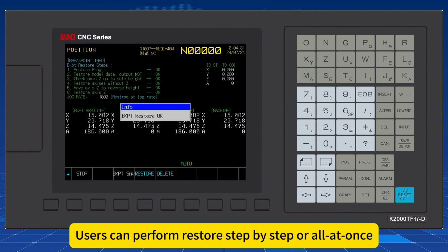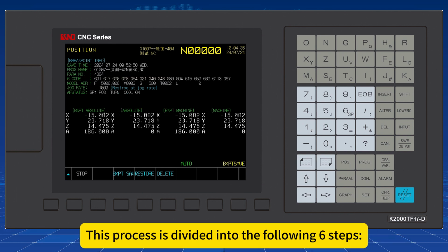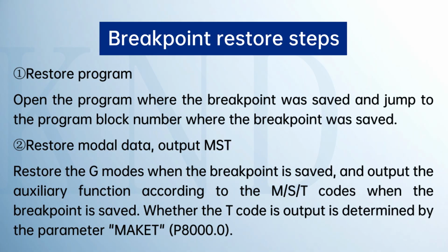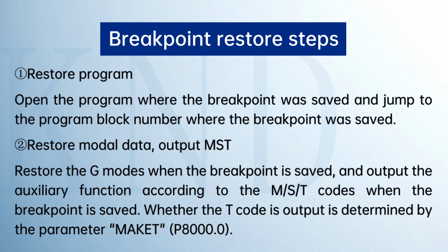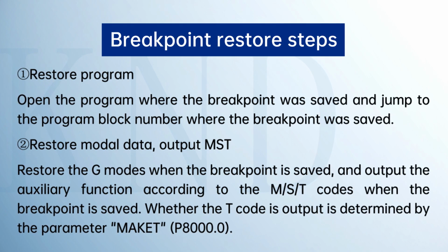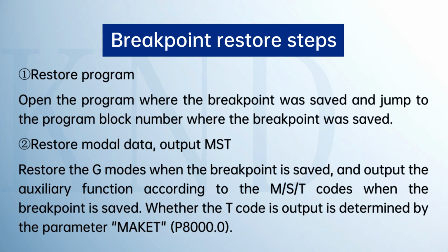Users can perform restore step by step or all at once. This process is divided into the following 6 steps. 1. Restore program. Open the program where the breakpoint was saved and jump to the program block number where the breakpoint was saved. 2. Restore modal data, output MST.